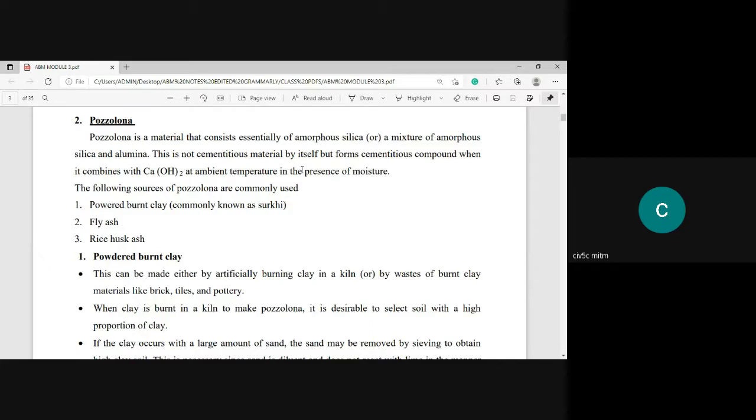They perform the X-ray diffraction analysis for this pozzolana, and from that they assess whether it is amorphous or non-amorphous, that is, non-crystalline or crystalline. Next, as I stated, whatever pozzolana material you are using, if it wants to react, I need to combine it with calcium hydroxide. Why? Because it is predominantly silica and alumina. It comprises more silica and more alumina. It doesn't contain calcium oxide or hydroxide. Did you get my point?